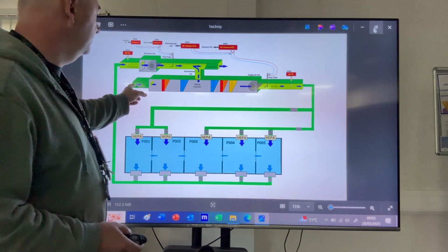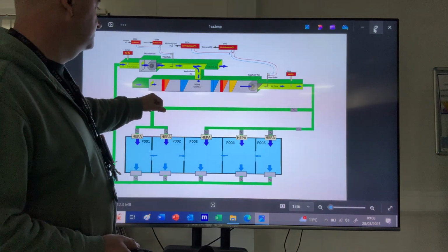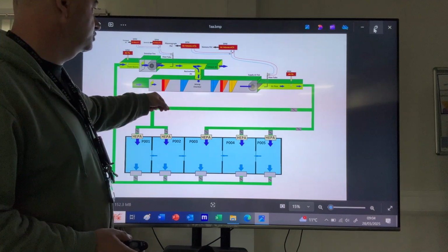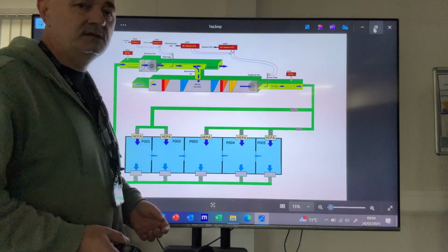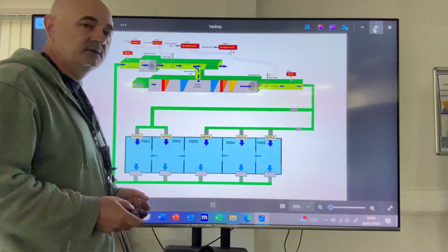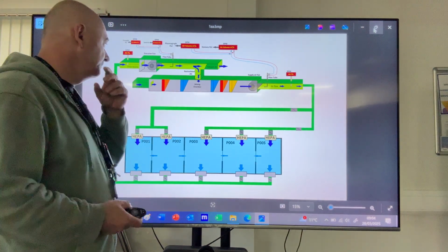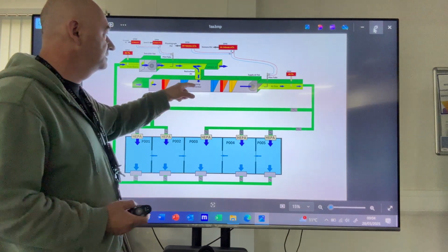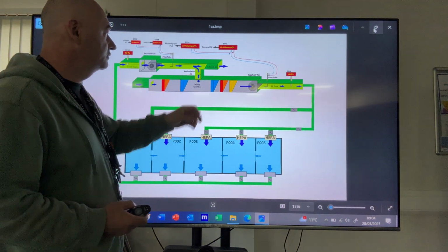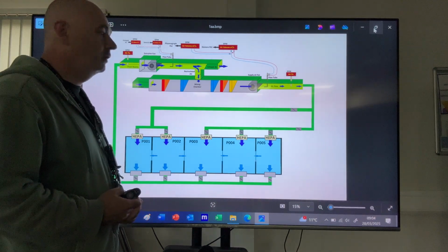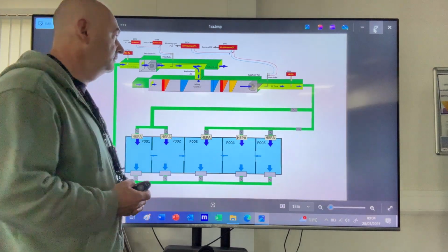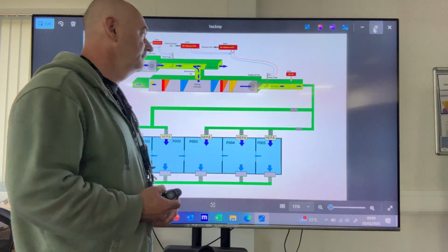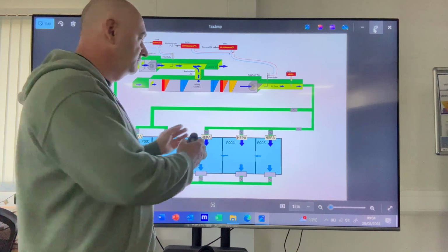It's very clear here, the fresh air which comes inside the AHU passes through the frost coil, which is used to protect the equipment when the temperature outside goes below zero. Then we have the pre-cooling coil, which is the fresh air conditioner, and then it immediately mixes with circulated air, and both go through the main cooling coil, which technically is supposed to be only a trimmer, then to the main heat exchanger, then the humidifier, and then it goes through the main airflow duct into these branches, and it goes into